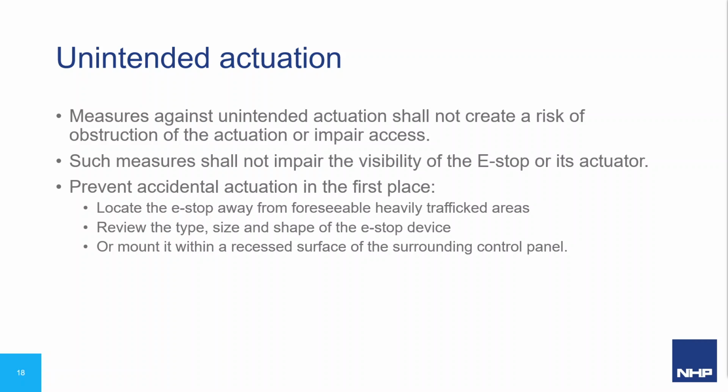One of the main gripes of requiring an emergency stop is that at some point or another, someone is going to hit the e-stop in a non-emergency. This could easily be done purely by accident. If the e-stop is located somewhere where someone may bump into it and shut down the whole machine, this kind of nuisance tripping always spells bad news for production.